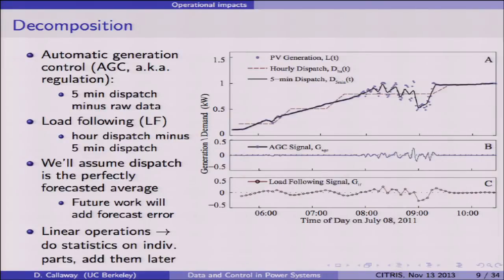So what we did is we took, for one individual PV system, we produced a time series that looks like its average over an hour. And one thing I didn't say before is that there are 20-minute ramps in between. That is, if the hour ends right here in the middle of that ramp, there's 10 minutes on one side and 10 minutes on the other of ramping between the averages. And system operators think about that for net demand as well.